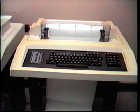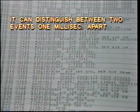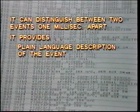The SER is constantly monitoring the status of each input point and prints out a detailed record whenever the status changes. A typical SER printout gives the exact time of the event down to the millisecond. It can distinguish between two events occurring 1 millisecond apart. It provides a plain language description of the event,